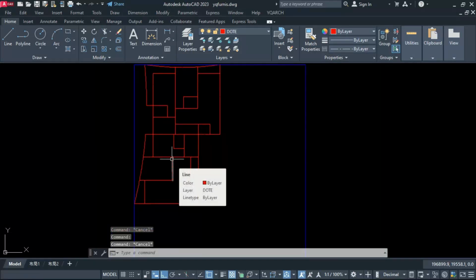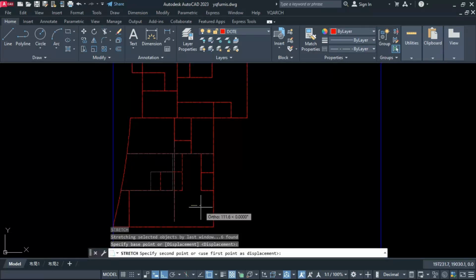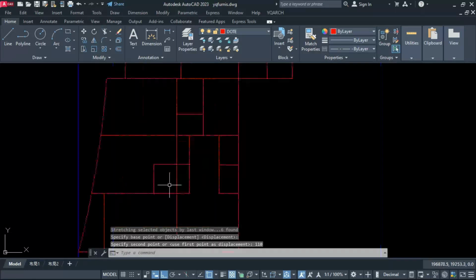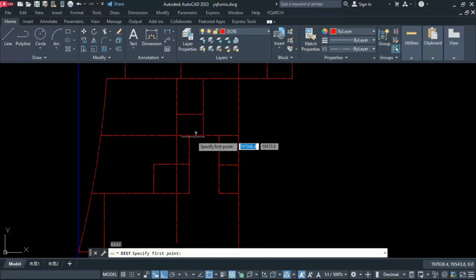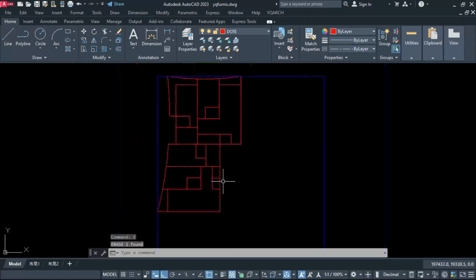If you see here, we are getting our planning something like this. So this balcony not required, will keep as it is. Okay. Number of two flat apartment. Let this here 110 centimeter. So we are getting wider space. Minimum we are required 120 for access. Let this here little bit more.